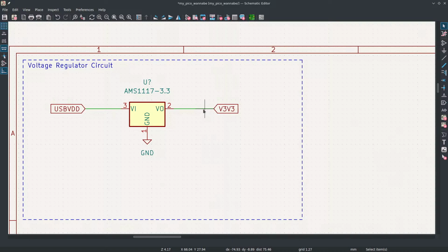So these linear voltage regulators are super simple, super easy to set up, great for when you have very low power that you're going to use from their output, but they are really bad for anything that you need to draw a lot of current from. They're very clean power though. So everything's a trade-off.